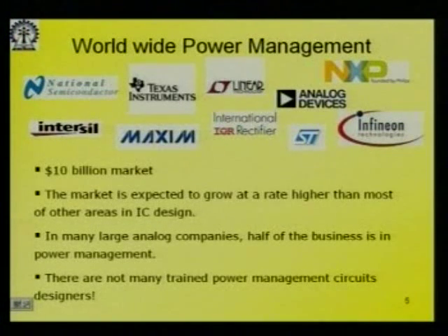They need to have a lot of experience in working with hardware and making sure that the circuit works, because power is something which you have to very carefully control, right? Even a few percentage loss or reduction in efficiency can heat up certain portions of your circuit, or there could be certain transients and spikes which might destroy your equipment, right? So all these things can happen.